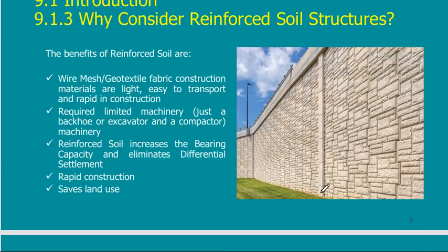This is another shape of the wall. These are all the parts of the facing. Facing are just simple. Don't imagine that they are retaining walls. They may be something like 10 centimeters to 15 centimeters, something very, very trivial, corresponding to a similar retaining wall that would be maybe 1 meter thick to carry a considerable height.